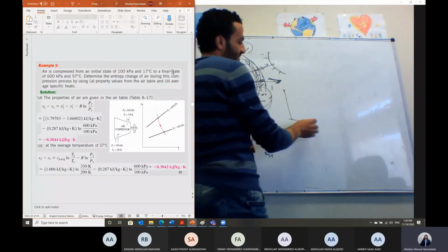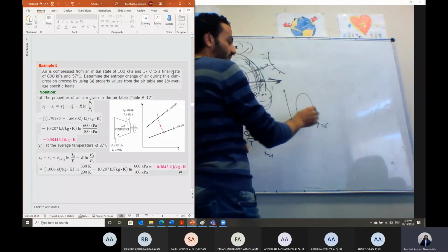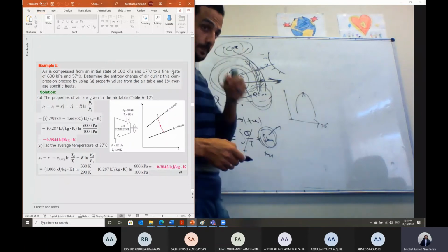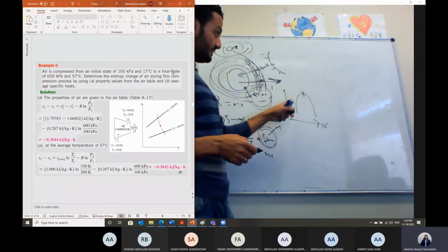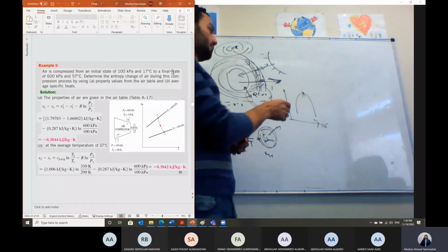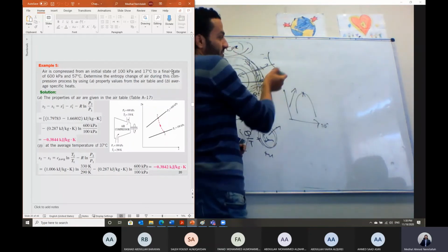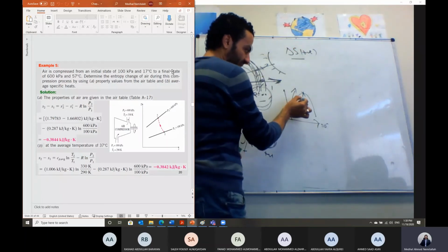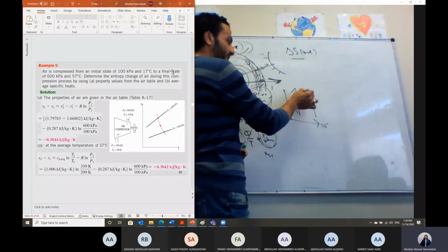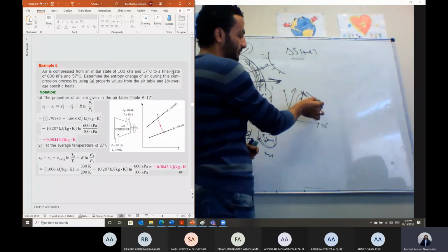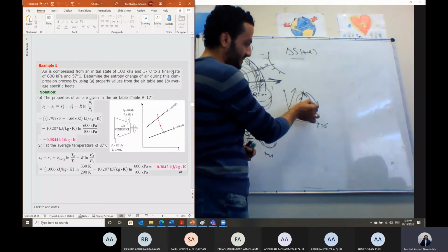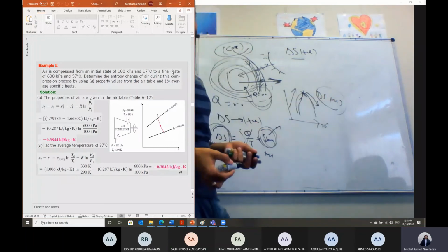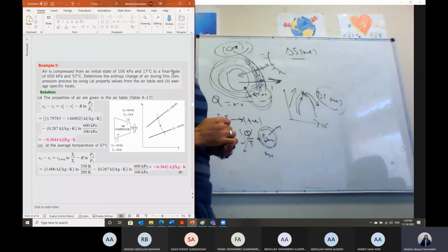And there is some idea I believe in. If you look at the entropy curve, it is a curve with a point here. The point is that the curve is flipped. So usually if you are going in this direction, based on the second law of thermodynamics for an adiabatic system, delta S should always be positive. So we are moving in this direction until we reach a critical point. At this critical point, we cannot move further on, because any movement here in this curve will result in delta S as a negative value, and this does not satisfy. This is a clear violation of the second law of thermodynamics.